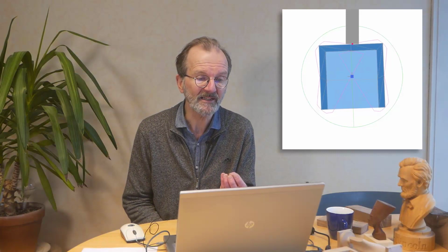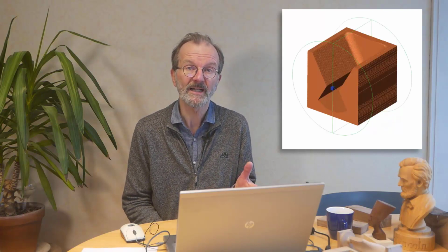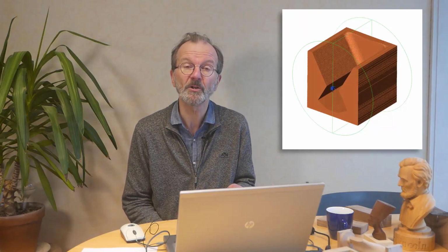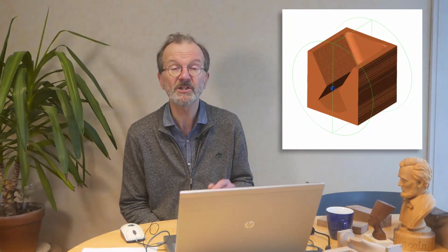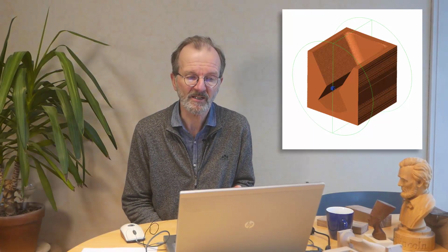It doesn't look entirely logical perhaps, but when you see the cutter move along the part, you see that the toolpaths are correct for the center of the tool. However, as you can see here, for the inside of this particular part, the situation is different. DeskProto simply cannot reach all parts of this geometry, and so much material will remain uncut. That's an undercut area. So the simulation shows a result that is completely different from the part that we wanted to machine.